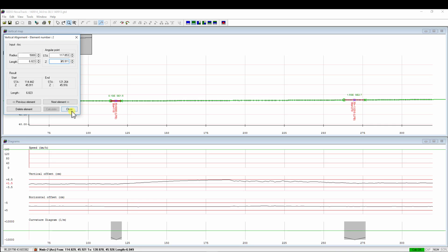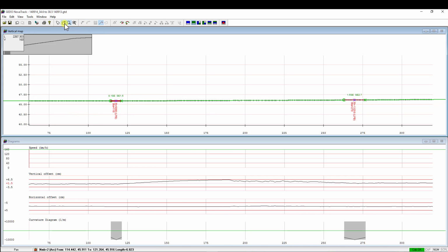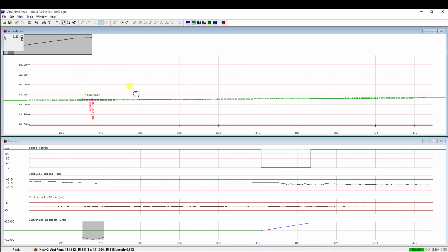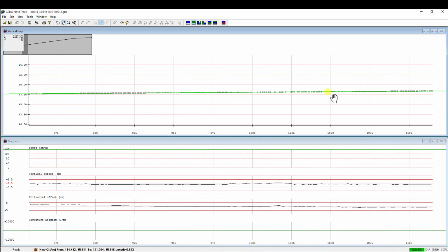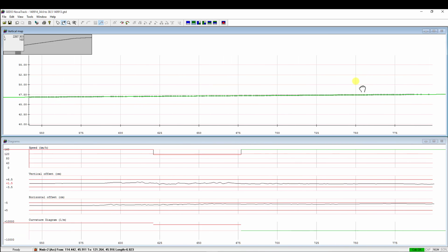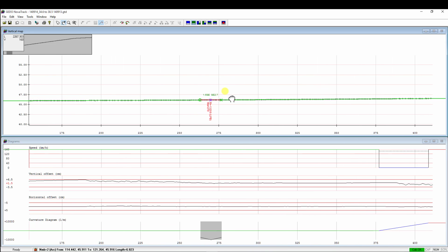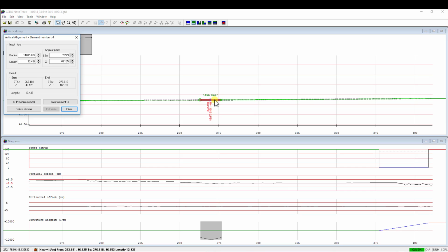However, you can continue adjusting using the elevation or the chainage. So if you highlight the parabola, the STA is the chainage, so you can adjust the chainage either by clicking on these arrows or just typing in the value.